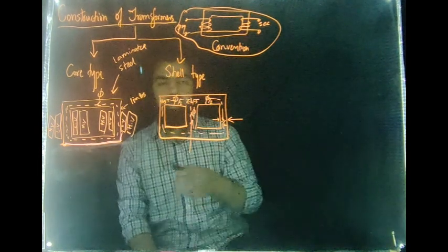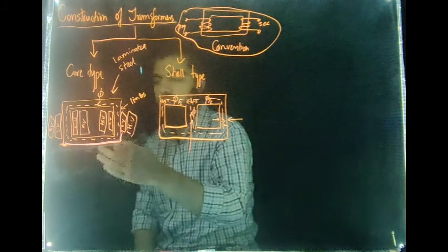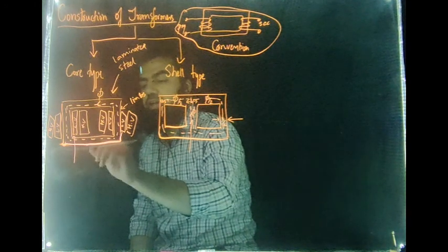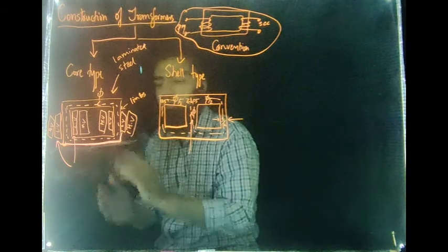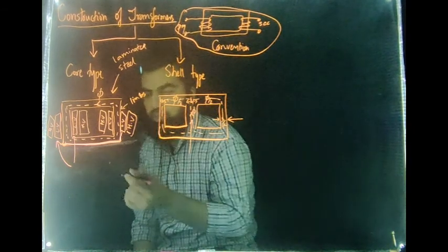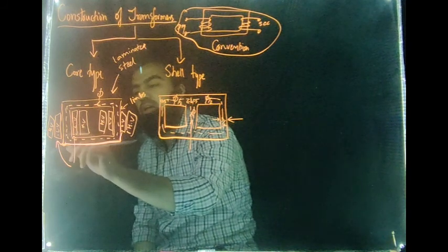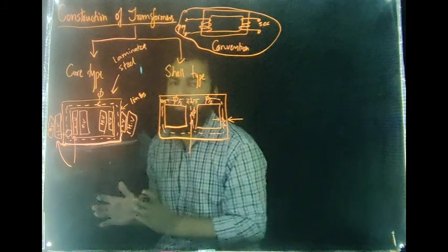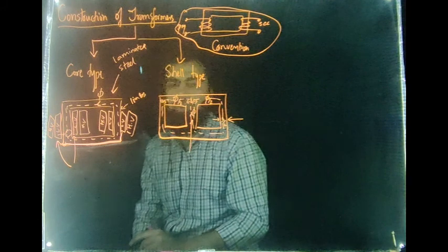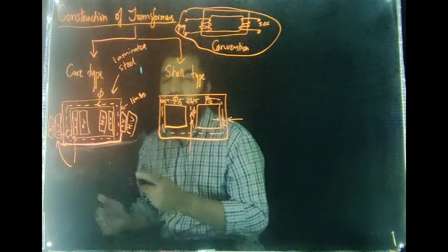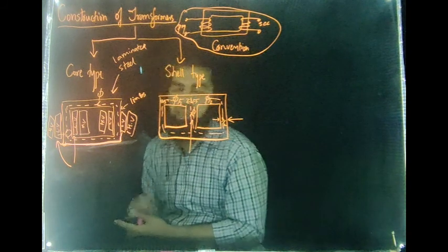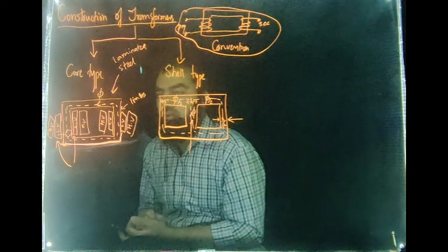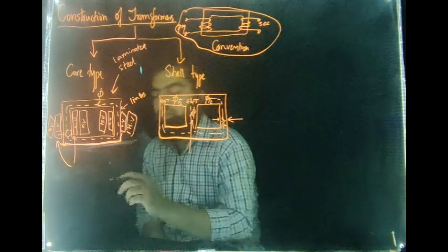By winding in this manner, with the low voltage winding being internal towards the limbs, you can note that the potential difference between LV and the core of the transformer will be less as compared to the potential difference between the HV and the core of the transformer. Right? So if the potential difference is less, circulating current will be less. Also, with winding the transformer in this manner, the insulation requirement will be less.